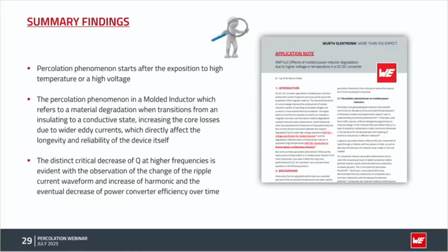Which kind of material are you using? The size of the material. What was the pressure that you used to create the components? We're speaking about new technologies on molded inductors like co-sintered transfer technology, hot molding, but even though everything is related, because at the end we have a coating layer, we have some glue in between, we are using organic combination with non-organics, and to guarantee for sure the soft saturation, but on the other hand we can suffer percolation.